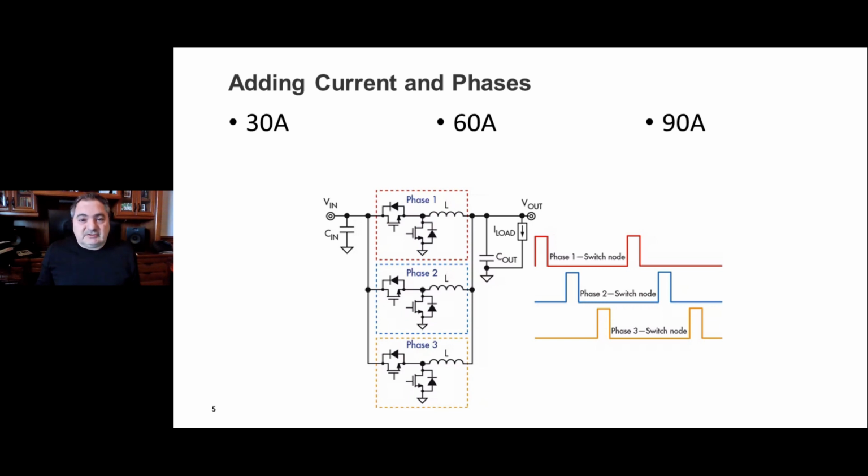Lots of power management vendors do this. This is how we add more power to a power supply to provide more continuous or instantaneous power. We add another phase. A vast majority of manufacturers have multi-phase technologies, and they can provide a discrete solution or a module or combination thereof. You could have a discrete control of power stages, which are integrated. But the phase is going to be a power stage and an inductor. And every time we need more current, we need to add a phase.